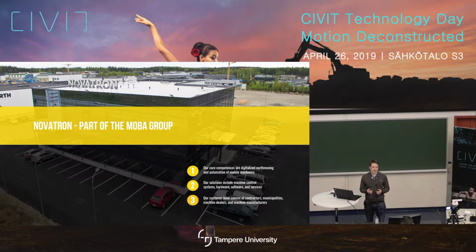So basically men with measuring sticks and laser measurement devices coming after the excavator to do measurements of the actual surfaces, and if something was not correct, they would just tell the excavator operator how to make it correct: you need to fill this area with 10 centimeters more sand, or take 10 centimeters out from this area. So with our tools, this part can basically be left out, and the operator can directly do the work accurately.